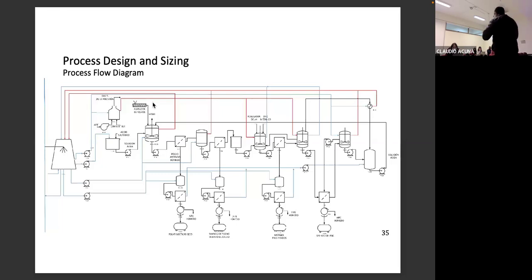When you say it would be an agitated reactor, or a solvent extraction unit, then you can determine the equipment cost. You don't need to determine all the costs. You don't need to go to the pump level. Remember, depending on the readiness level, you have 40–50% uncertainty. Just here you have 10%. So when you put numbers, don't put decimals, don't put dollars, put thousands of dollars. You see 5.63, it's ridiculous, it's not correct.